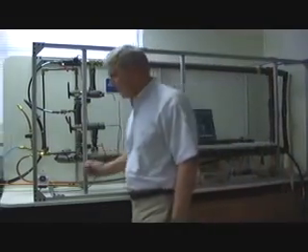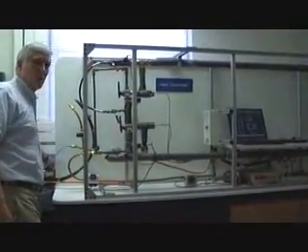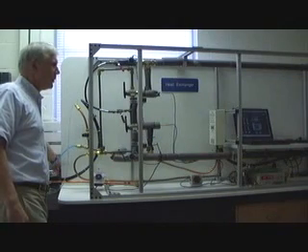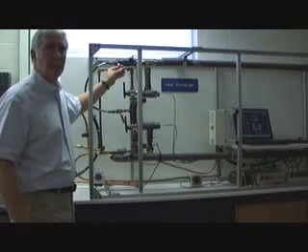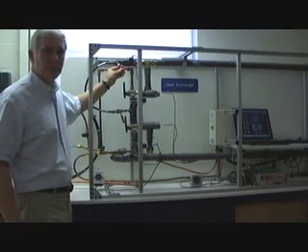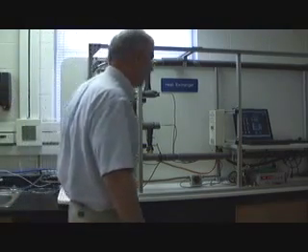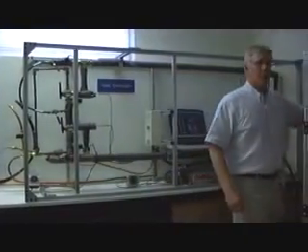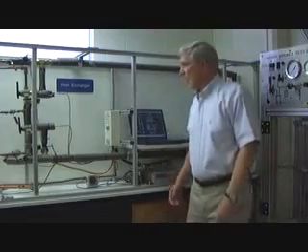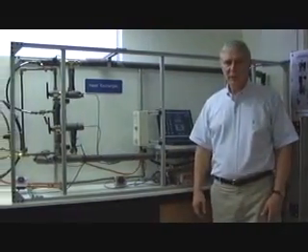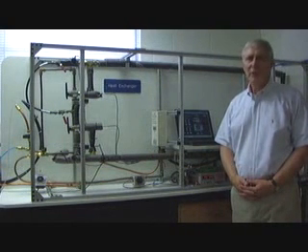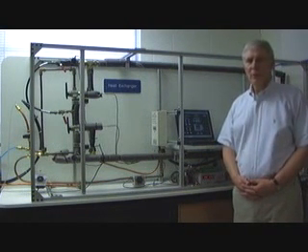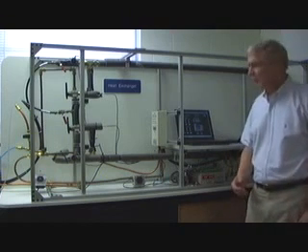Once you've done that, come over here, turn on the water at the main water valve and adjust the flow rate by looking at the flow rate on the computer screen and adjusting these red handle valves. Turn on the hot water heater using this handle right here on the wall, and then we'll wait for the system to come to steady state. Steady state should only take a couple of minutes, maybe even seconds at the most. Once it comes to steady state, begin collecting data.